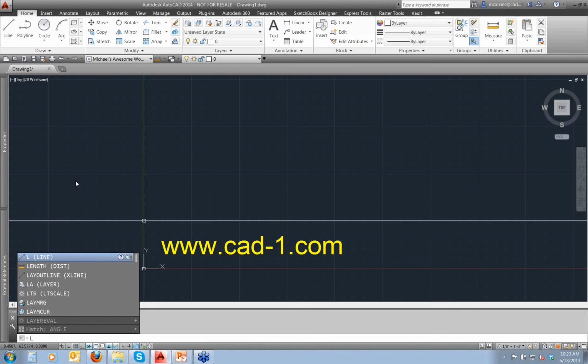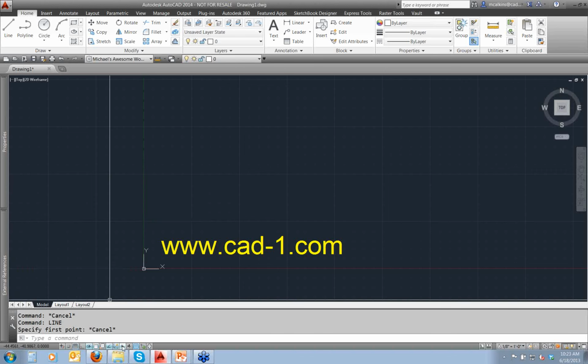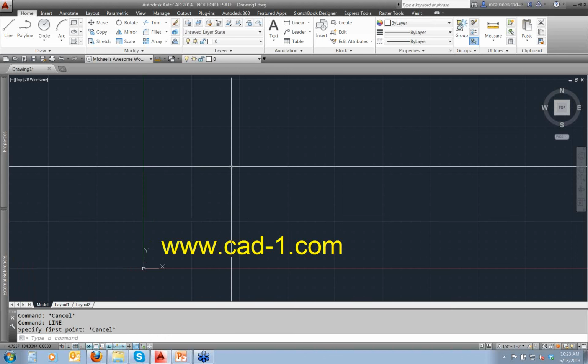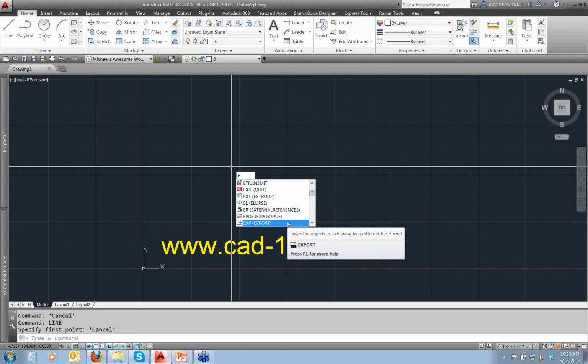If those letters represent an alias for a command, it will show those first in the list. It'll default to those, and you can just hit enter. But what's really nice, and this also happens on your dynamic input, is that it also gives you a list of other commands which start with that letter or letters. This can be nice if you're using one of those really long system variables you wanted to type. I tend to forget sometimes some of those less often used system variables.